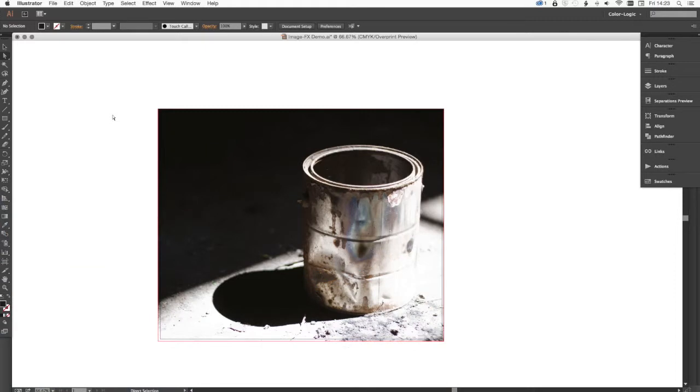The Image Effects plugin is an extremely simple tool to use, and it will automatically calculate the metallic effect for your image and for the different pixel values in the image. However, what it won't do is design the file for you. To get an image to work really well in print, you need to think about contrast, having areas inside the design that are metallic and some areas that are not. So simply running the plugin doesn't give you the perfect image.